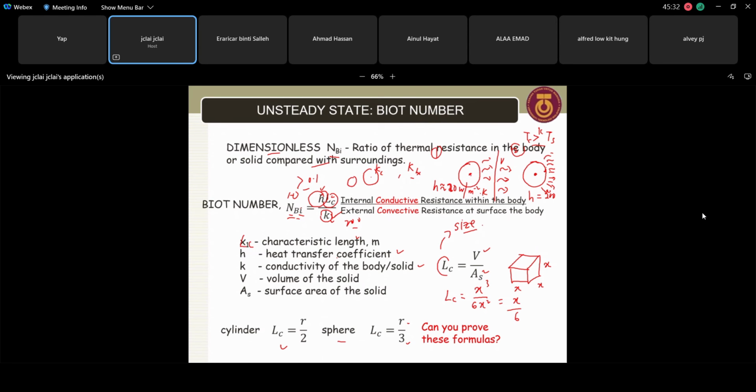Heat can be transferred from the center to the surface fast enough to compensate the heat loss to the surrounding, to maintain the temperature of the whole body at the same T. So under this situation, the whole copper ball can be assumed as a same-T body.